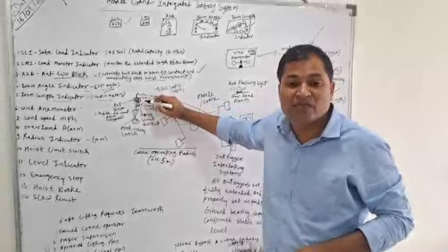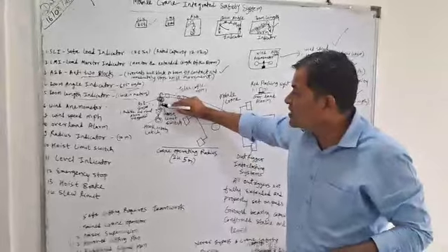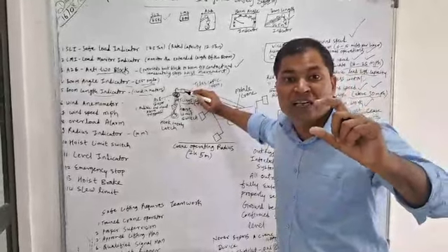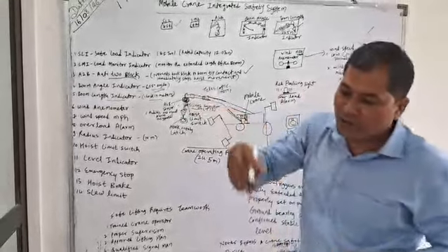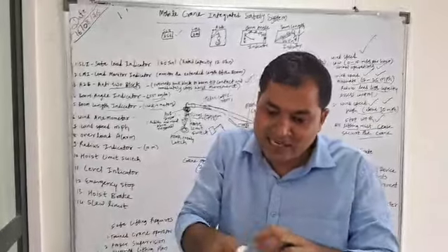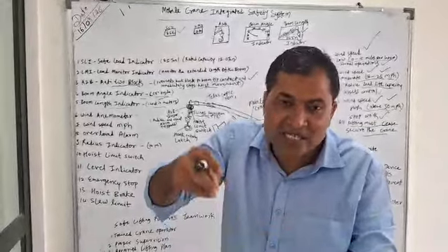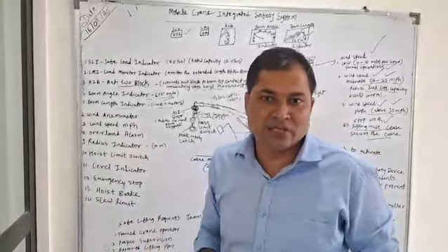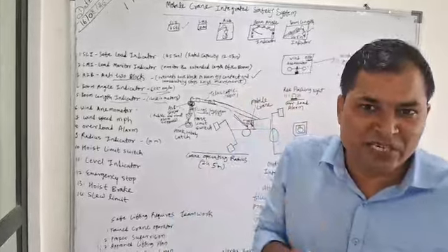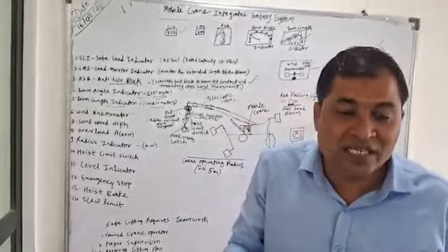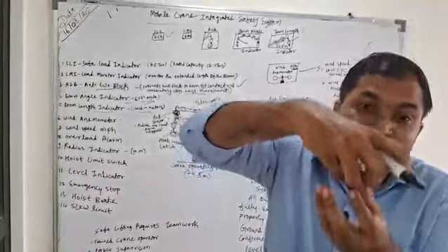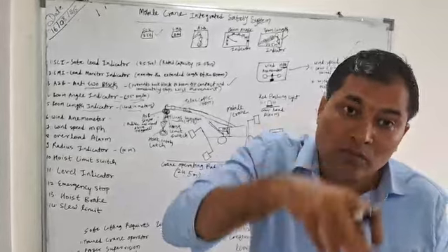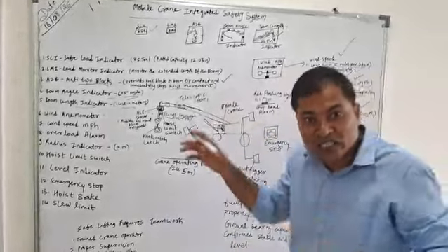Third party inspection is very important. You have to go for third party inspection of these slings, so you know what amount of load you can lift with them. Because if you want to lift 9 ton, 10 ton, and in between the slings get a jerk and break from the middle part, there is danger. So always you have to go with third party inspection to check the load lifting capacity of the slings and the load lifting capacity of the hook block as well. The TPI, third party inspection, is also very important for the hook block, for slings, and for other things as well.